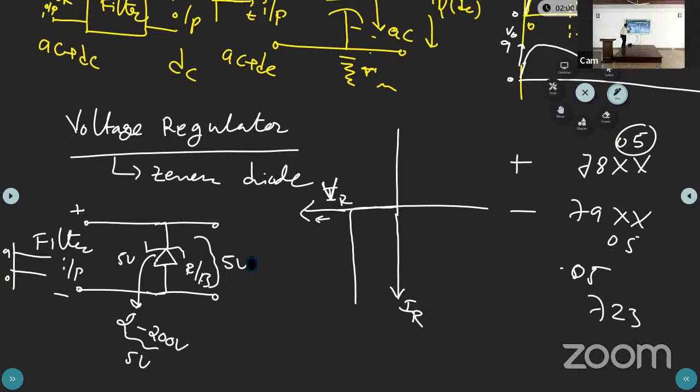This is not the applied voltage. The applied voltage increases; we are applying 9 volts. But at 0.5 volts, conduction starts and the current increases. How much current is present? That whole current can appear in the output circuit, but the voltage is constant. Because the output voltage stays constant across the Zener diode, the Zener acts as a voltage regulator.